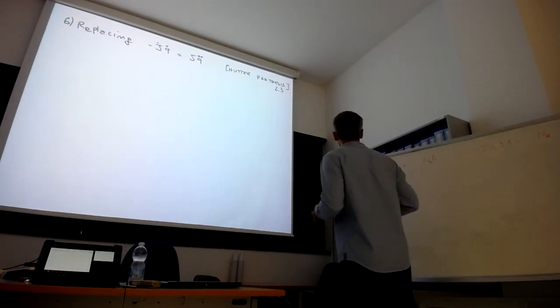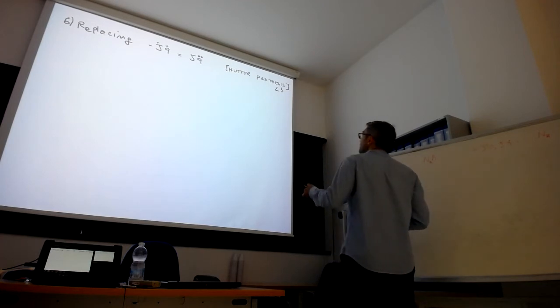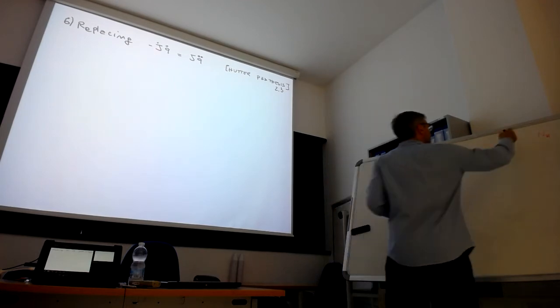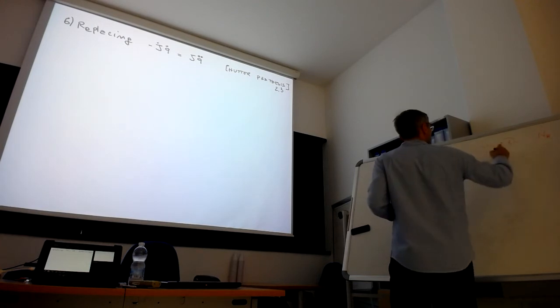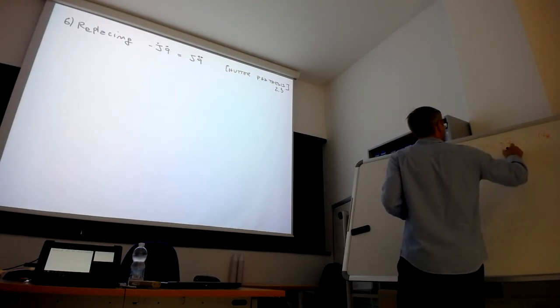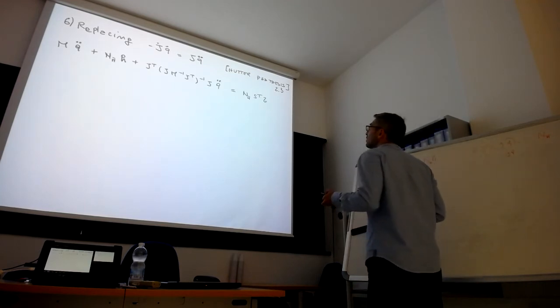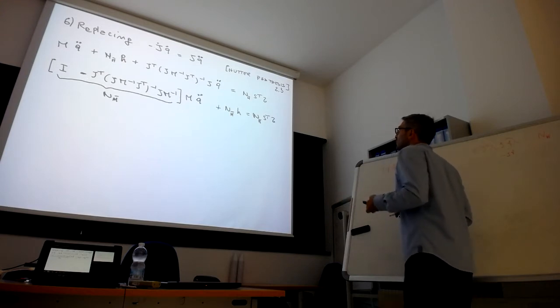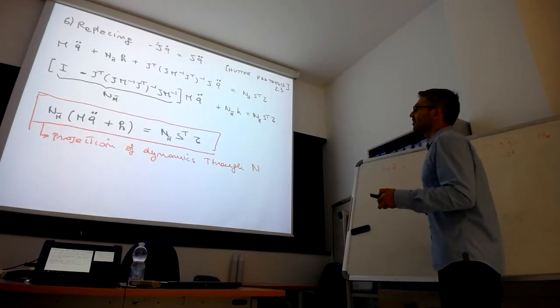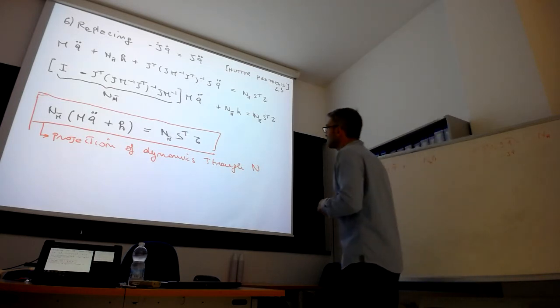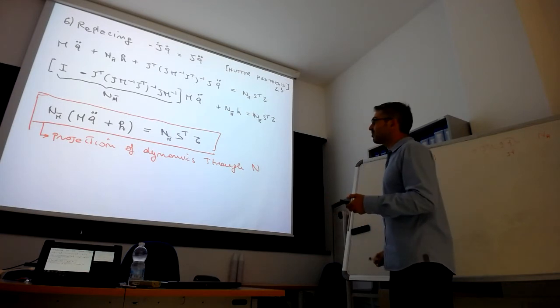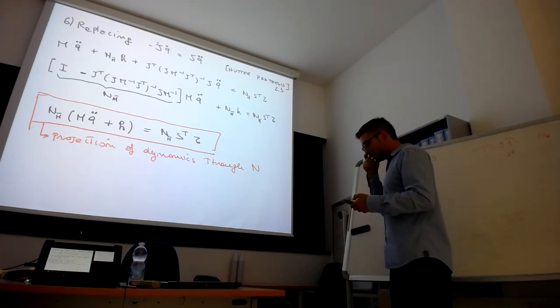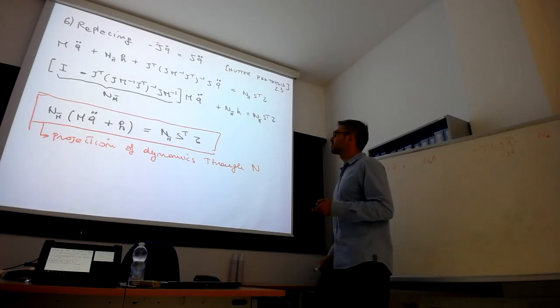There is a way to simplify this, replacing, for example, this ugly term, J dot q dot, with minus J q dot, and we see that we can simplify this equation more, and we get the null space projector outside this term times this. So it's like multiplying left and right hand side for the null space projector. It's like projecting all this equation in this contact consistent subspace.